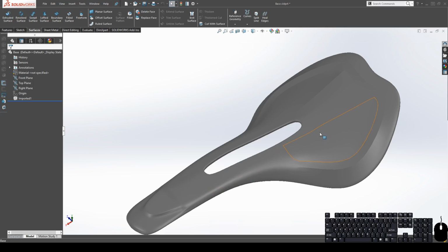And fortunately with SolidWorks, they have what's called a built-in Parasolid kernel, which ensures that most faces in a model behave like a piece of cloth cut from a larger patch of fabric. There is magic inside SolidWorks that allows for each face to untrim itself up to the original patch from which it was cut. So this is what SolidWorks can precisely extrapolate from this untrimmed result. For the rest, it will be precise until the boundaries of the original patch are reached. After that, it will guess the rest of the shape or simply stop in cases of singularities.